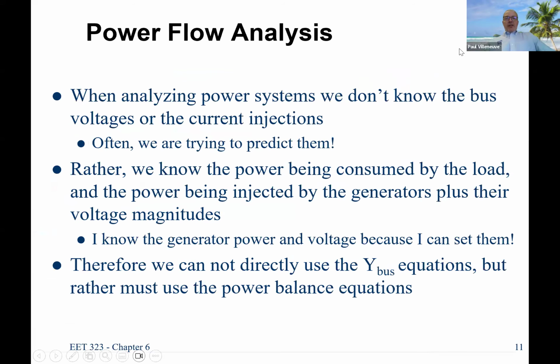So what we left off with was if we knew all the bus voltages, we wouldn't need to do a load flow. We could calculate currents and get power flows throughout the system. But generally speaking, we don't know what the bus voltages are, so we need to have a way of calculating them. Because knowing the bus voltages, both magnitudes and angles, and having a system model, which means having Y bus, we would be able to calculate all the power flows.